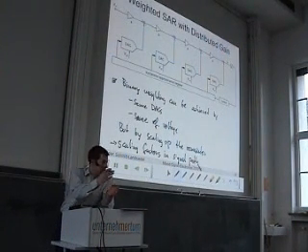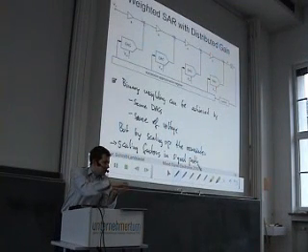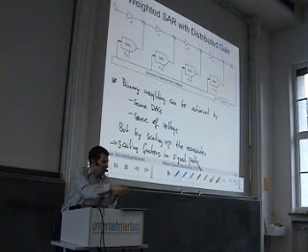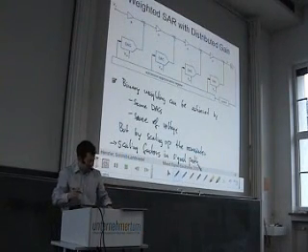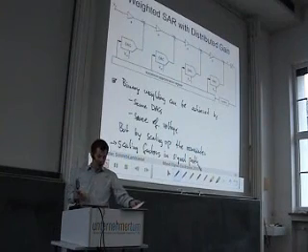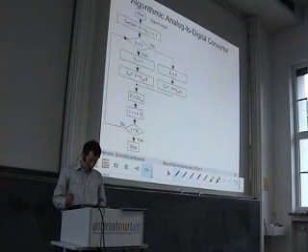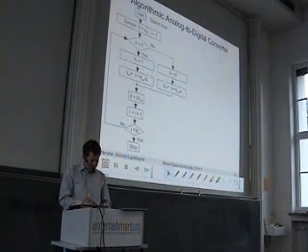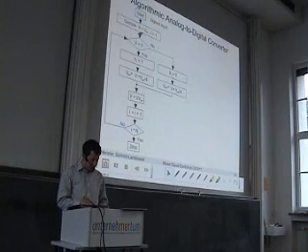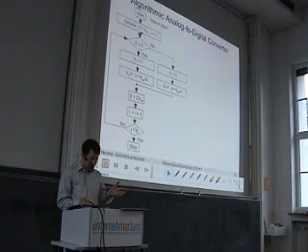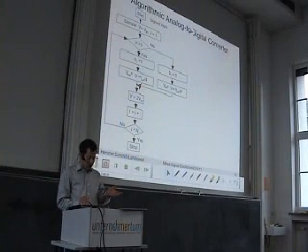Okay? So we do a decision with a certain DAC, we take the quantization error of this step, and we bring the quantization error up to the previous level. Let me illustrate this with this algorithm. So you can see here we start exactly in the same way. We sample the input and have an internal voltage which is equal to the input signal. And then we check for the sign. Well, if we are larger than 0, then we decrement the internal signal by Vref/4. Otherwise, we increment the signal by Vref/4.